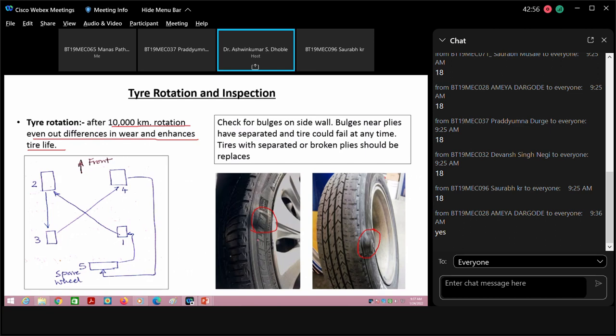And then he will fit the tube into that, and you can again use that particular tire for some more time, because if you don't have money to buy a new tire, then people used to do that. The problem with the gaiter is that whenever it touches the ground, it will change the stiffness of the tire. As a result, you feel the shock. Okay, that is the problem with the gaiter.